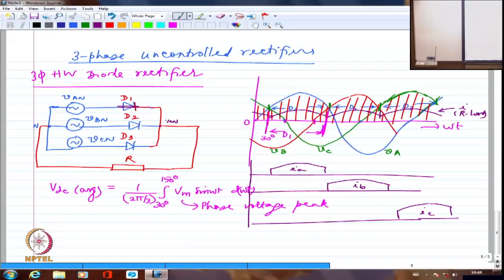So this really gives rise to, again, a huge amount of harmonic content, and without any negative half cycle, saturation of the transformer could very well be seen in this kind of rectifier. So this rectifier is really problematic because of these reasons. And one more thing is, without neutral, I can't work with this rectifier.